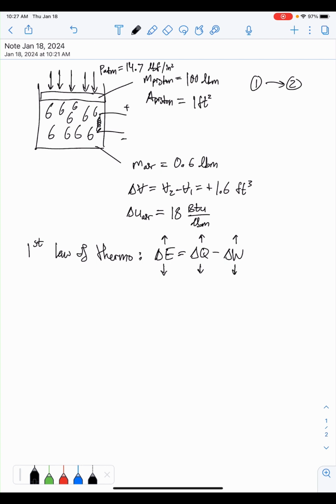Conversely, a negative work value, by the minus sign, actually means an increased energy. This means things like compression, for example. So when negative work happens to your system, it's kind of like receiving energy from the environment, like the environment compressing this system further, and you have more energy inside the system. So it's a bit odd, because I believe in some classes like physics, this would be positive, and the definition is switched, but in our case, it is what it is.